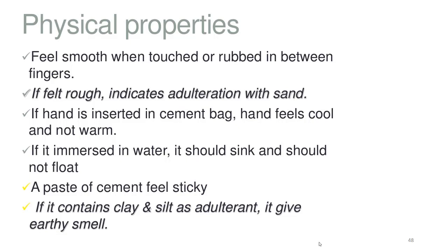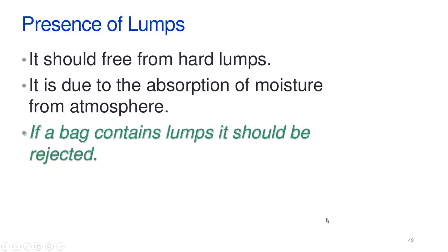You can also check the cement by its smell. If the cement smells earthy, it might be due to the reason that it has some clay and silt content in it as an adulteration. So you must not accept that type of cement with an earthy smell.